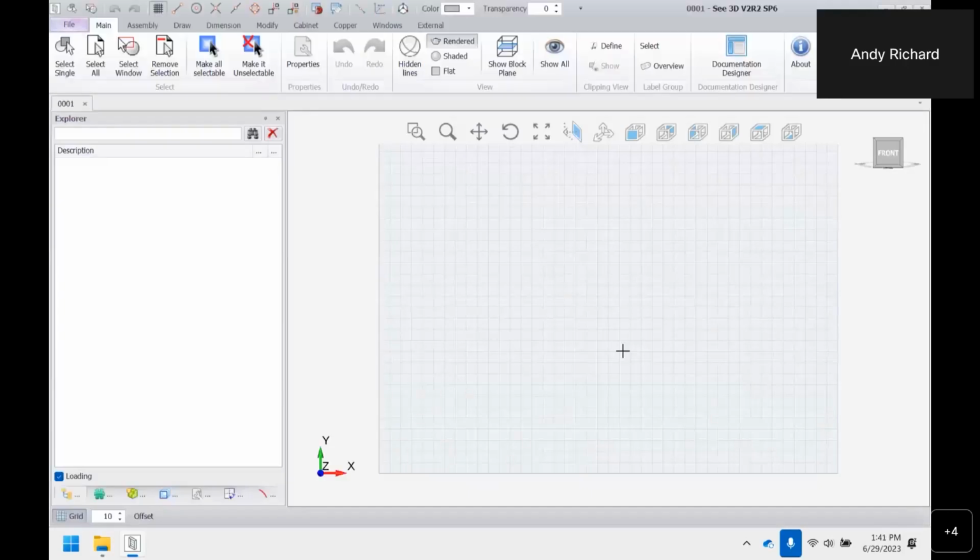We also have standalone because some customers want, like Brian said originally, to be able to take AutoCAD electrical drawings, export that data, and then use 3D. You can do that with standalone. You can import all the data, it'll populate the project, and then even the wiring will work. So it'll automatically export the wires, it'll do the cable routes, it'll do the component placement, everything.